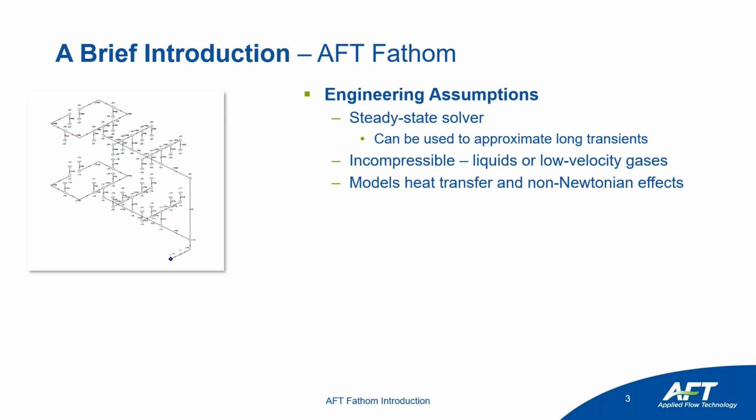AFT Fathom, while it is steady state and incompressible, will also consider heat transfer effects. So if you're looking at temperature delivery or ambient heat transfer, we'll touch on that later in the presentation. And then we also consider non-Newtonian effects. While most fluids are probably Newtonian, and in the case of Fathom, most systems are probably water flowing through piping, we can also consider things like sludge or other materials from mining, for example. Whether that's a pseudoplastic or a dilatant, or we have some models for paper stock, all of those things can be considered within the AFT Fathom solver.